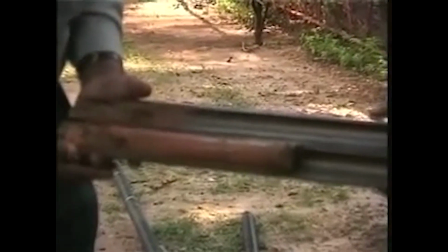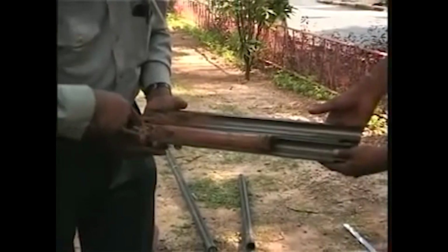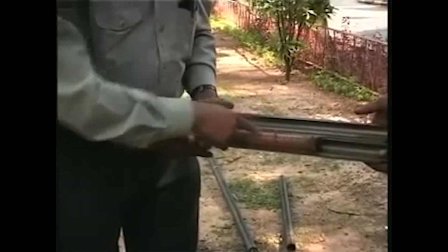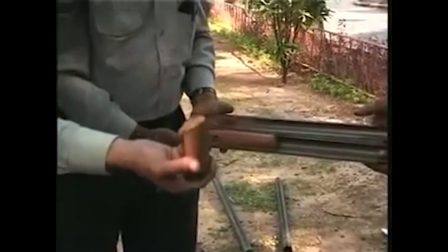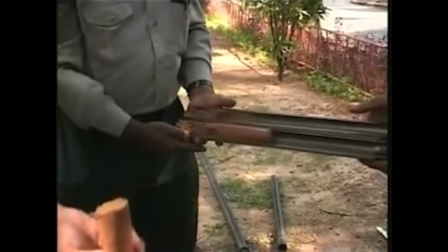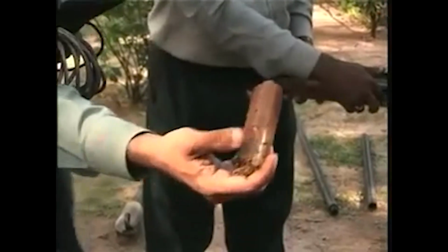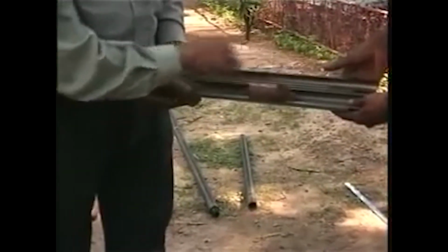So if you recall, this is the bottom end of the sample, and that is the top end of the sample, and you can see that the sample was moist near the top, and it was becoming dry as we went downward. So this has a lot of sand and silt and other fine grained soils. It has some cohesion as well, and that's how we identify the sample.